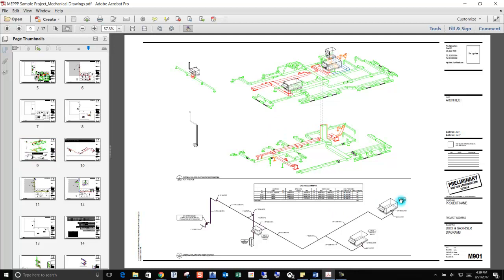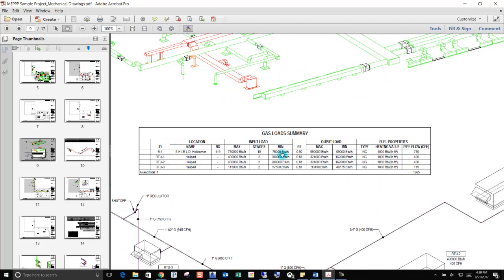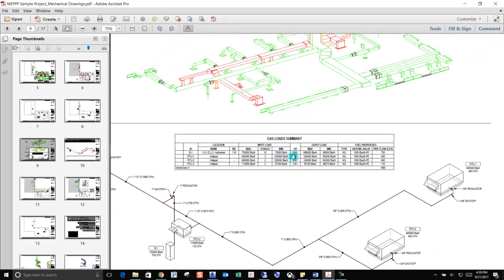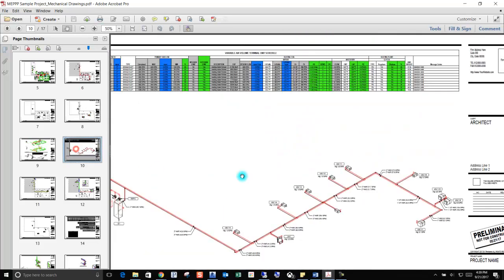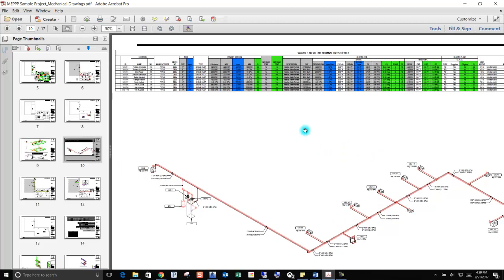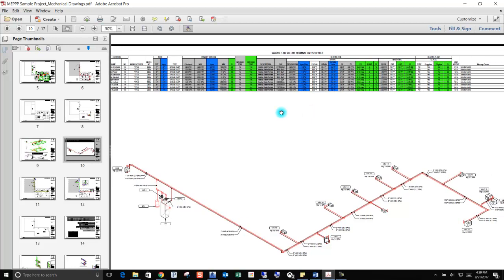And in some cases, what you guys will see in videos later on, we've included additional design schedules that may not end up on construction documents, but certainly serve a purpose of training people on how these families are doing the calculations. So that's what this is here. Same with the hydronic side, so we have our VAV box design schedule shown here. So you can see this is an auto-sizing family, which you'll hear more about, but essentially it's showing you what the calculated values are, what requires input, and what is an override. So inputs and overrides are essentially these blue columns.